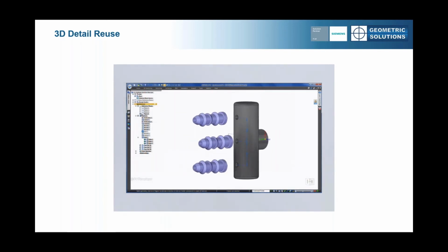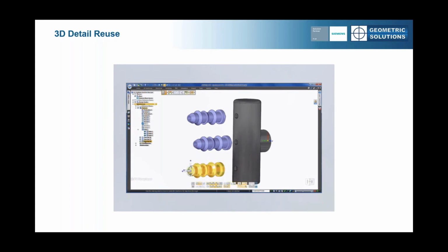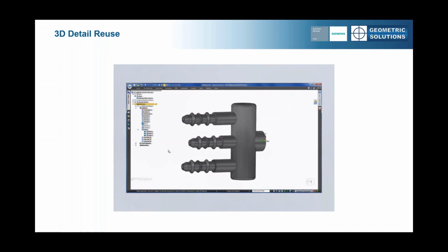Now that we have the barbs in the correct location, we need to figure out how we're going to attach the geometry to the part. Luckily, there's no need to worry about such things as Boolean operations, as Solid Edge will take care of this. Watch as it automatically extends to connect to the solid geometry. But what happens if we realise after pasting these barbs that we want to move them, perhaps to help hose clearance?